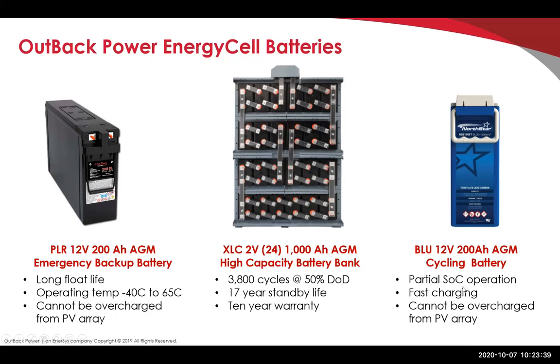It has a partial state of charge operation. So it suits off-grid applications, or where it's going to see a lot of partial charging, or if you're doing time of use where you're cycling. Also, you could do some really fast charging. You can charge it really fast.